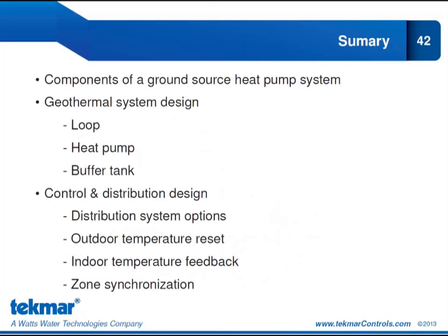Lastly, we took a look at the control and the distribution design. So we looked at what are our distribution system options? What kind of terminals can we choose that operate well with the low supply water temperatures? And remember, it's important to have those low supply water temperatures or low entering load water temperatures, because those are what are going to give us the highest possible efficiency in our heat pump.